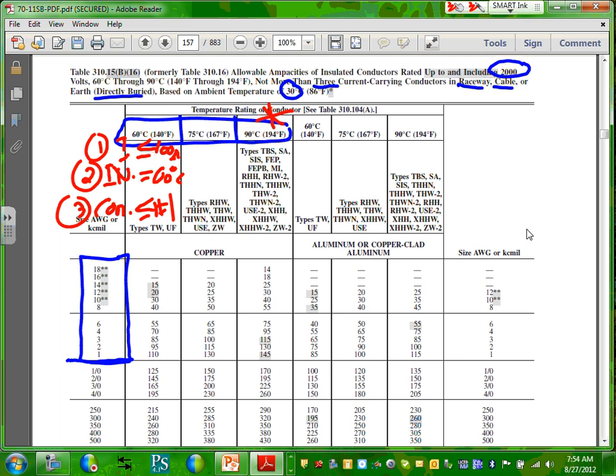That's why I highlighted these up to number 1. Equal or less to number 1, you're defaulted to the 60 degree, unless you know that the lugs on both sides of the conductor are 75. Can I have thumbs up that we understand the rules of using the 60 degree column? Everybody's okay with this? Okay, these are very important, guys, to know.